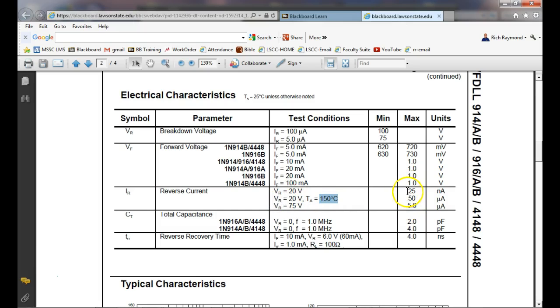So here we're going from what? 25 nanoamps, and we're going to be up to 5 microamps. But we're going to measure across that 1 mega ohm resistor, right? You understand? We're going to calculate the current. We should see where it starts to break over. So we'll use 3 power supplies, at least.